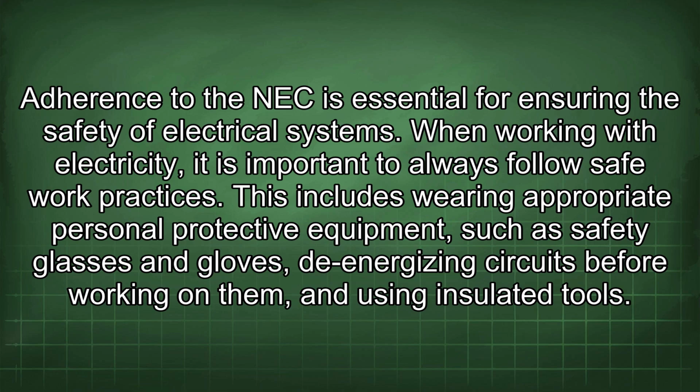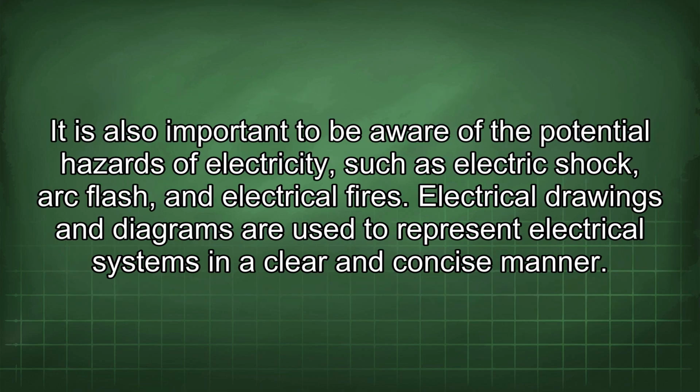When working with electricity, it is important to always follow safe work practices. This includes wearing appropriate personal protective equipment, such as safety glasses and gloves, de-energizing circuits before working on them, and using insulated tools. It is also important to be aware of the potential hazards of electricity, such as electric shock, arc flash, and electrical fires.